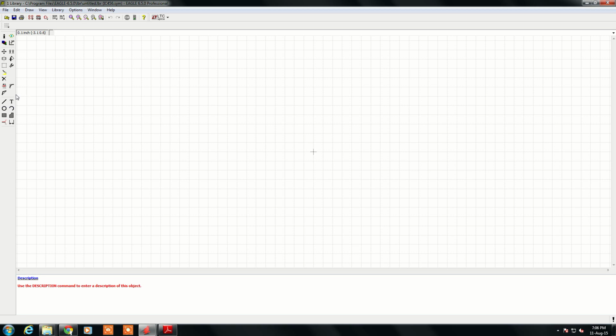As you can see, on the left side you have the wire tool to draw the symbol of the component which you want to create. When you draw the symbol, as you can see, we are using the symbols layer. If you want any inclination, you can use the inclination whenever you change the side.